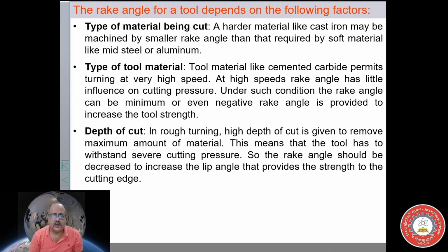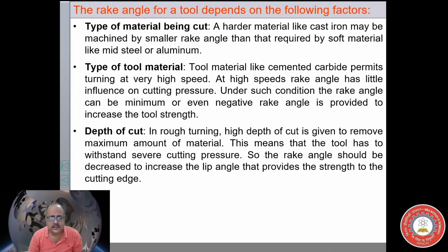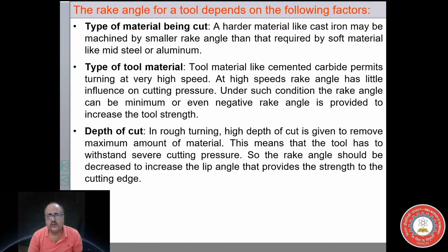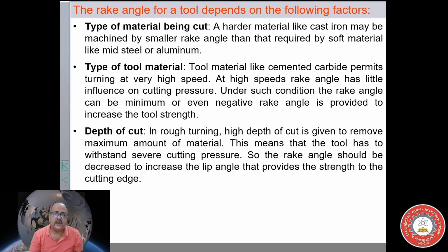The depth of cut, how much depth you are applying. Say if the depth of cut is more, obviously you should select a lesser rake angle. That means the load that will be applied by the workpiece on the tool will be high, so it requires lesser rake angle or negative rake angle.